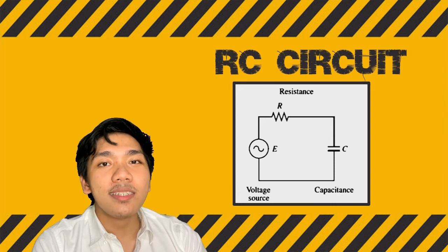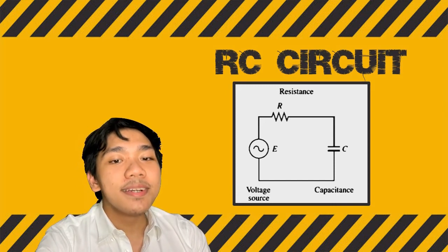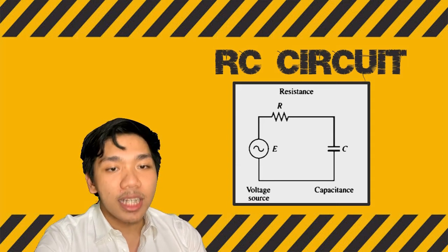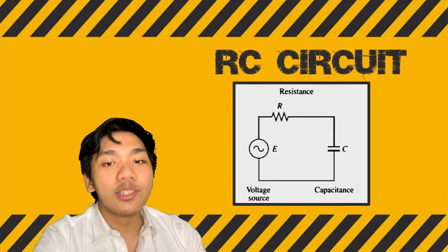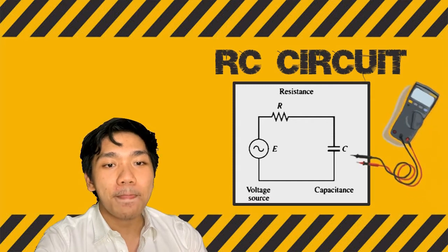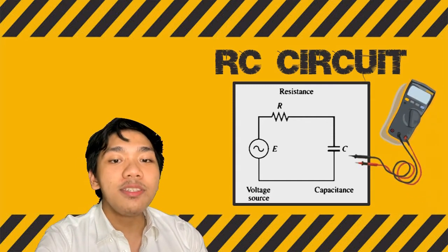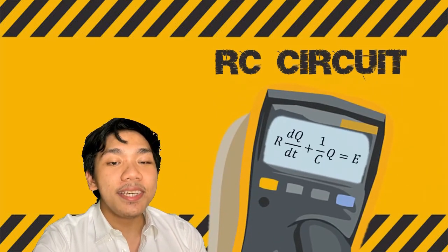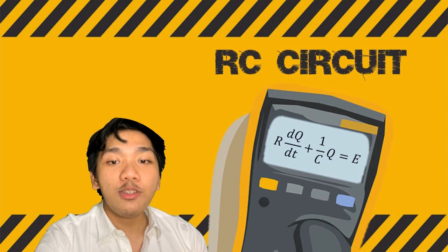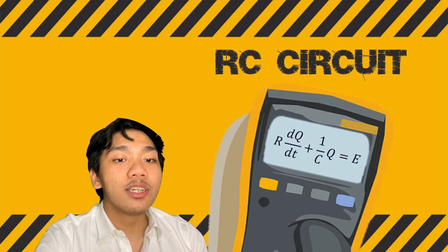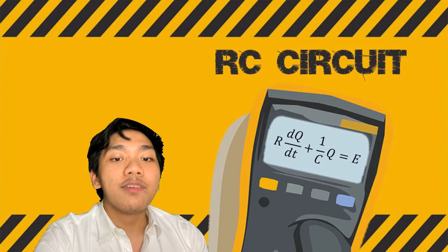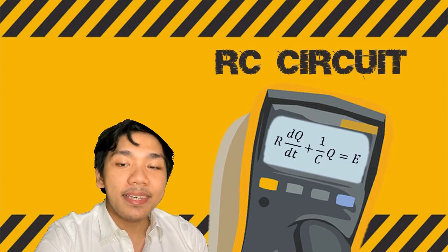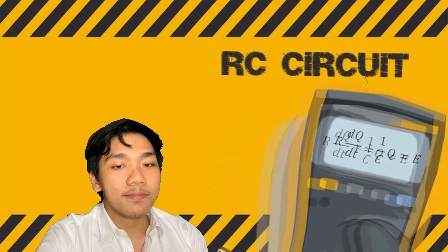The next one is the RC circuit. It is a circuit consisting of a simple loop containing a capacitor and a resistor in series with a voltage source, as illustrated by the diagram being shown. It is also evaluated using the formula given by Kirchhoff's law, which is the total voltage E is the resistance R, ohms in units, times the derivative of the charge Q, coulomb in units, with respect to time, plus the quotient of charge Q and the capacitance C, which is farad in units.